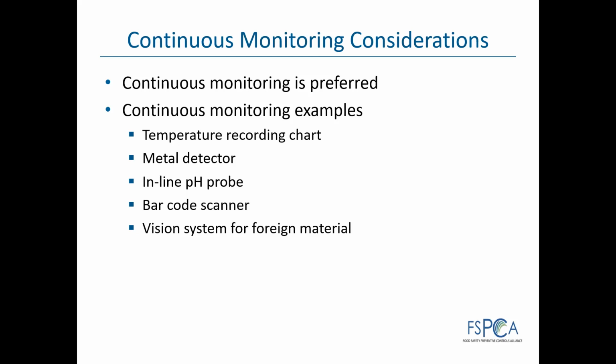If we are testing oxidation reduction potential in a fresh produce water system, you can't just rely on the machine to do it, because once your organic matter has accumulated, the ORP value is even much higher than at the beginning. However, at that moment, the free chlorine concentration has actually decreased. So you have to be based on your food safety plan. The ORP, you have to test it by a human being, using a manual test to compare with the machine.